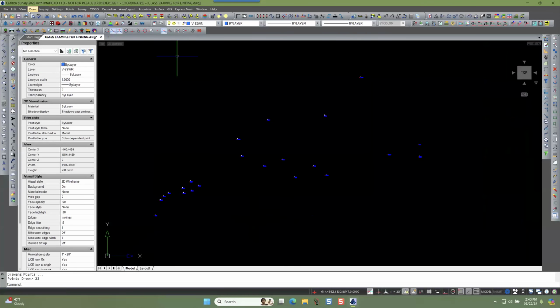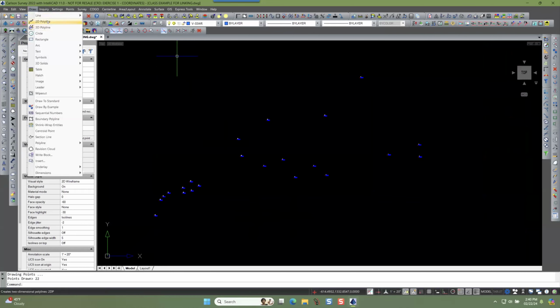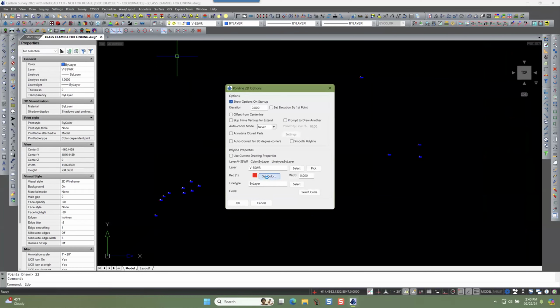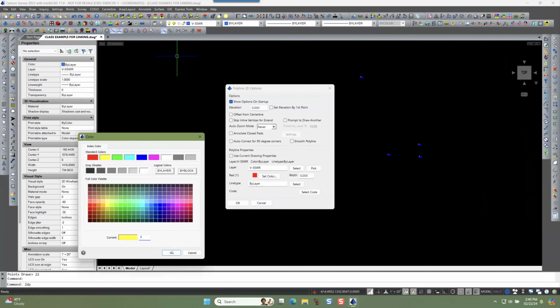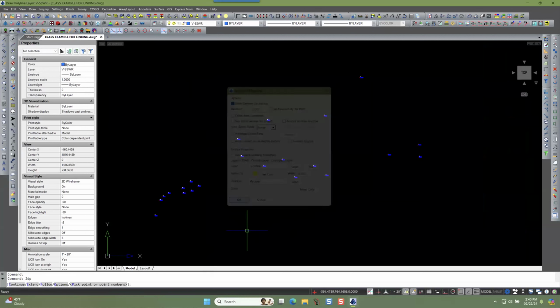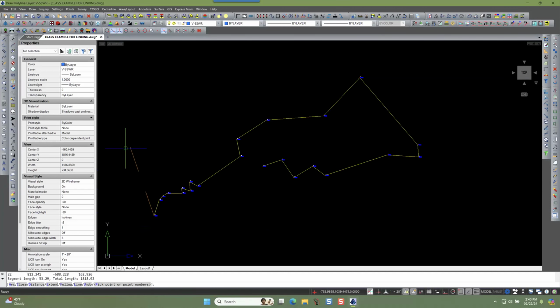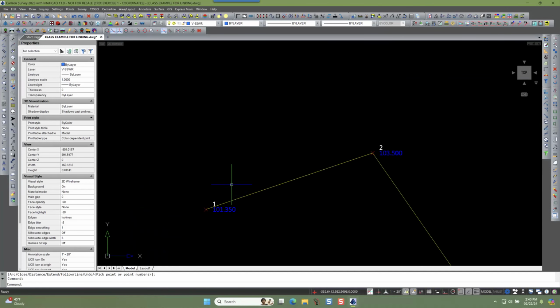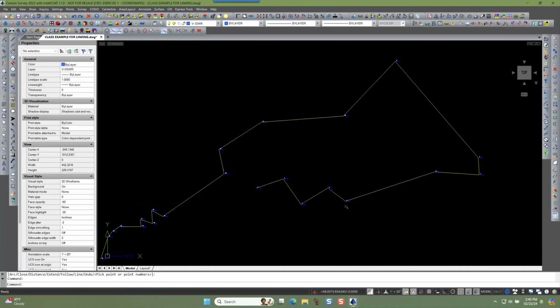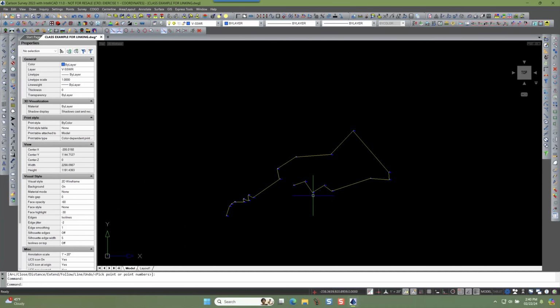So if we now go to draw a 2D polyline, and I'm just changing things around here. Pick point or point numbers. So if you said 1 to 22, boom, there it is, and it's waiting for you to keep drawing. You can keep clicking, or snap something else, but it starts at 1, goes to 2, to 3, to 4, and now it is 2D.